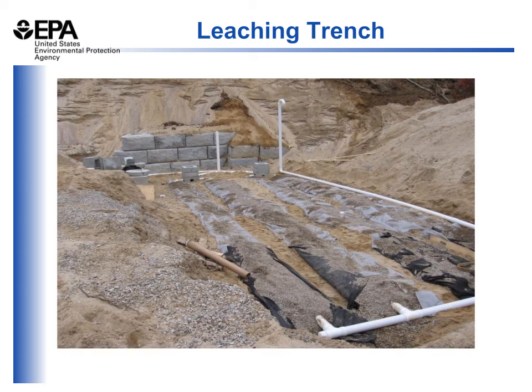The gravel itself is covered with a filter fabric, both below it and above it, such that the soils around the trench don't become clogged with any finer material that may exist in the naturally occurring soils. As you can see at the back end of the slide, there's a vent pipe that's installed to make sure that air can move in and out of the trenches on a regular basis.